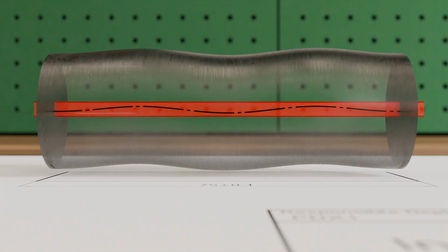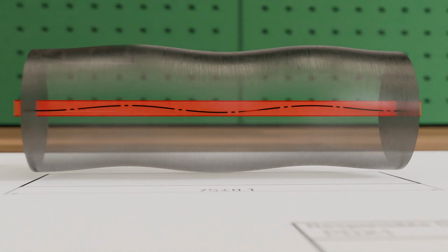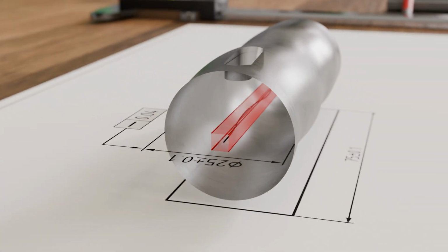This is similar to how we previously restricted the flatness of a surface using two straightness tolerances perpendicular to each other. However, this type of straightness tolerance is not very useful for rotationally symmetrical parts, because it results in a rectangular tolerance zone along the axis. That means the tolerance would be larger in the diagonal direction than along the edges of the tolerance zone.